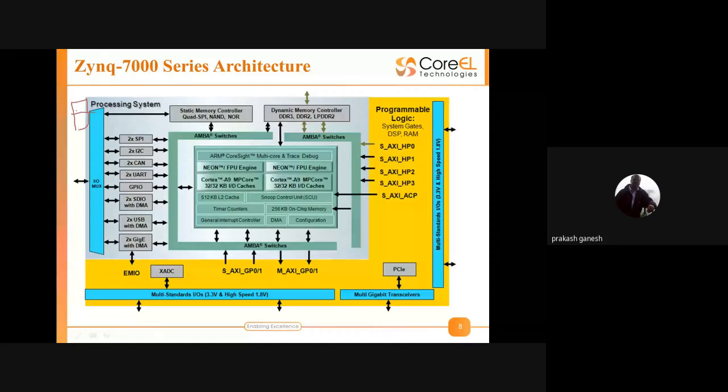We have an option here which takes care of generating different clocks from the PS to the PL. They are called PL fabric clocks. Those clocks are derived from the PLLs here and distributed to the FPGA, so they take care of synchronization also. But if you give clocks externally, it's your responsibility to take care of synchronization, constraints and so on. You should give them properly.